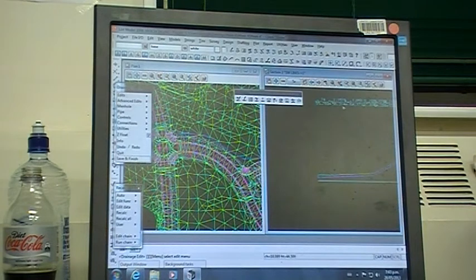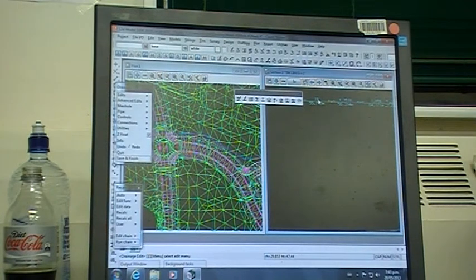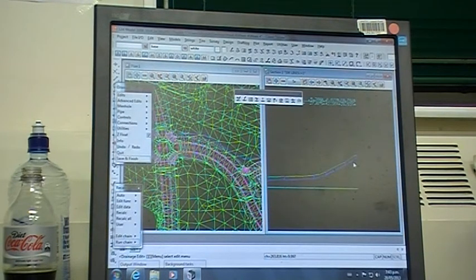They won't all be 1%, but the minimum will be 1%. So the flattest line has started off and said, okay, I don't have a lot of cover, I'll go at 1%, and that's the default. Based on what my minimum cover and minimum grade were, it now has a first crack at its alignment.